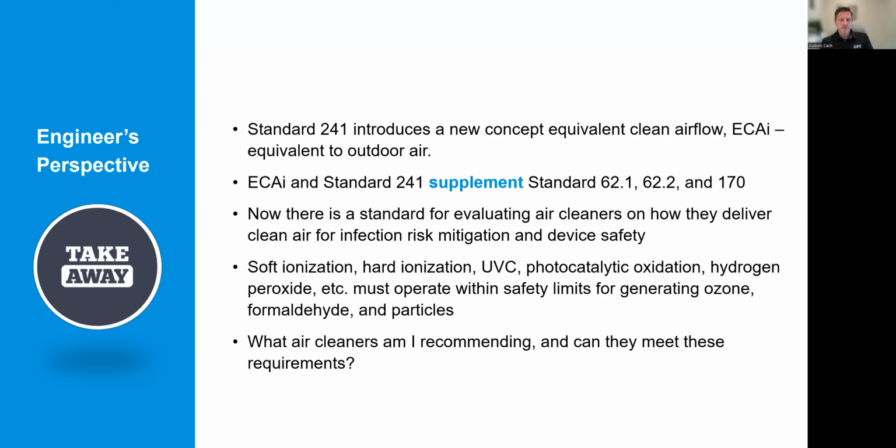So here's your first takeaway slide on the new content here. 241 introduces a new concept called equivalent clean airflow. The equivalent clean airflow math matters. We'll get into it in a minute. It matters when you're in the IAQP, which is the risk management mode. Equivalent clean air, or ECA, and 241 are used as a supplement to the existing ventilation rate procedures or the indoor air quality procedures.